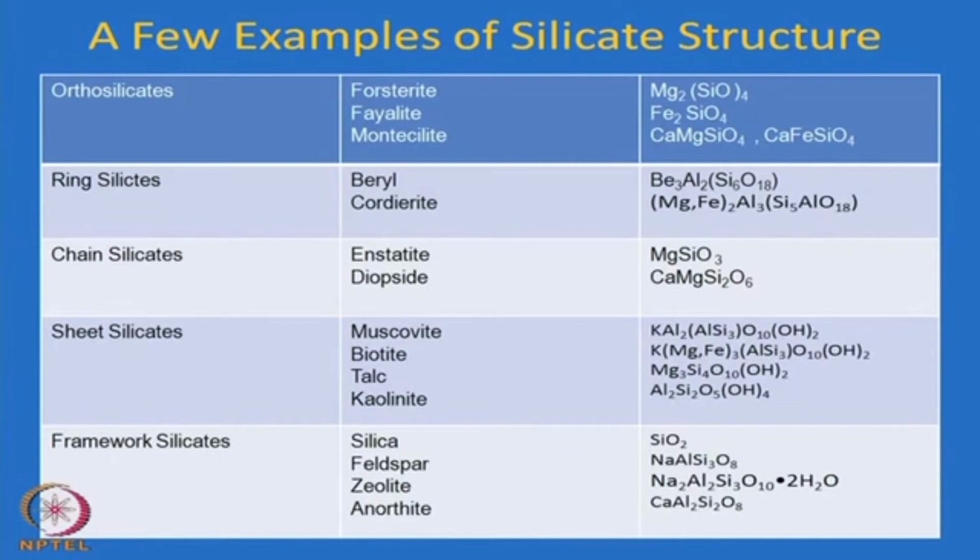Therefore, in many applications where the materials have to be heated and cooled several times, for example in furnaces, there are many products where all ceramics have to be heated to high temperature, and they have to be supported on some material, what we call kiln furniture. So, inside large kilns you have some kind of supporting system on which the actual products are kept, and it has to be used a large number of times, repeatedly, inside the furnace.